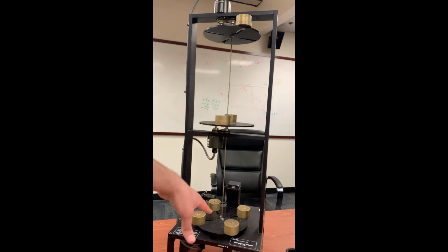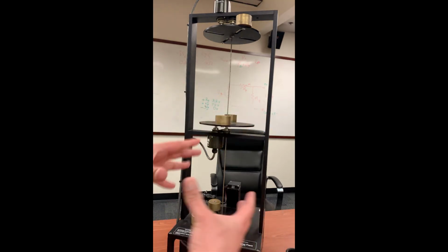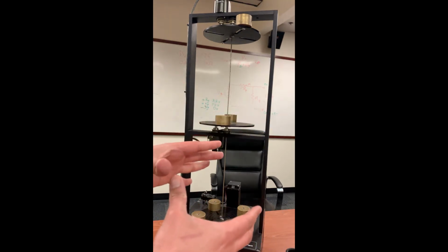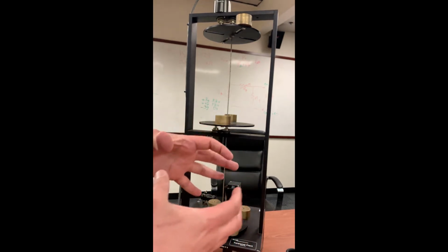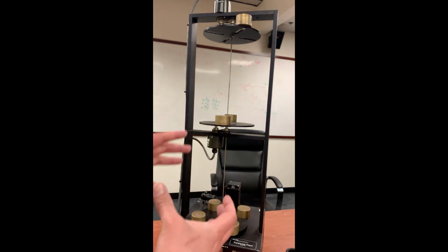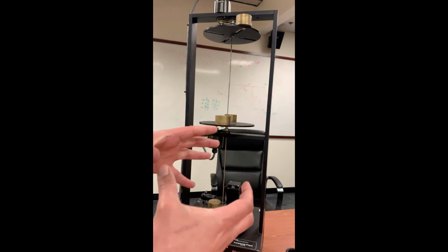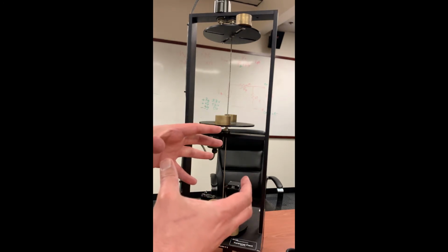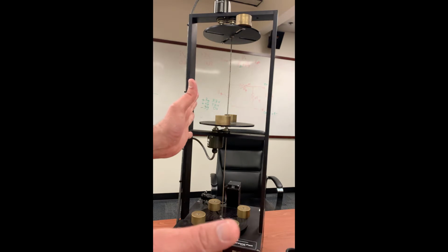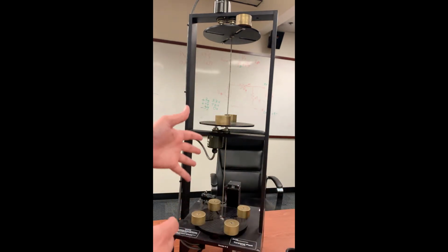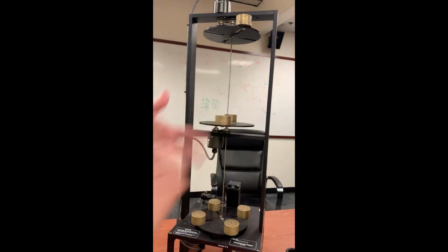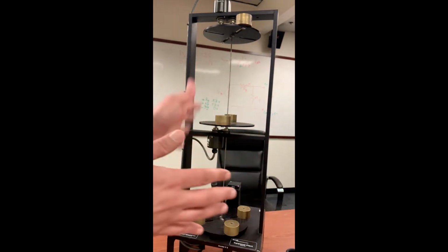So you can imagine that if I take the satellite and I rotate quickly, does it make sense that I'm going to impose that sort of potential energy in the springs, and when I get to the 30 degrees that I'm trying to point at, the springs and the solar panels are going to release, and they're going to then reverberate back into the satellite, and the satellite's not going to be doing a good job at pointing.